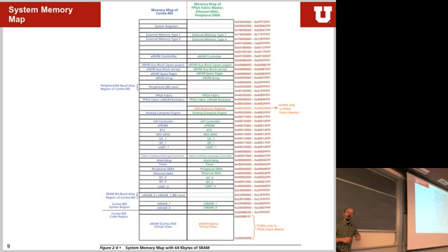Right? So now, oftentimes they have a trick. What they do is they have one of these registers in the background, but instead of just one of these registers, they have three of them. One of them will be the status, one of them will be the set, the other one will be the clear register. So they are all 32-bit wide.